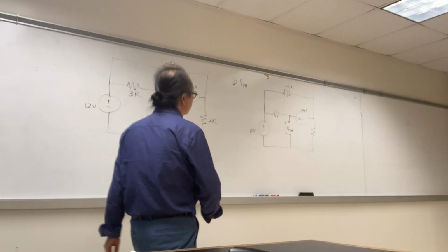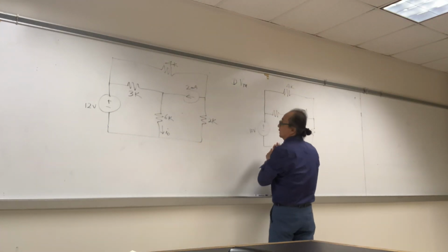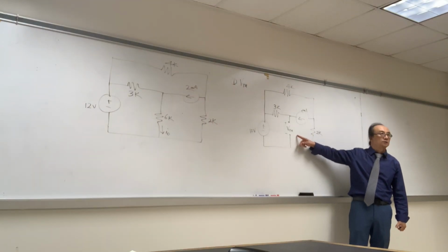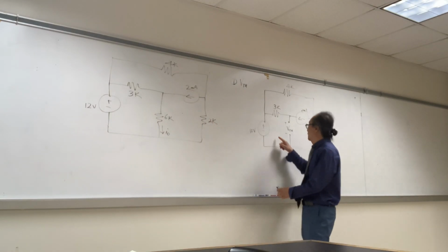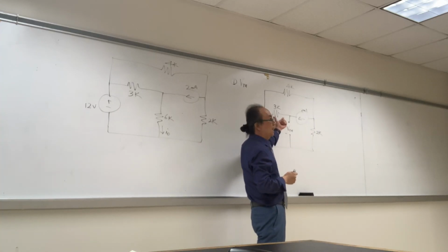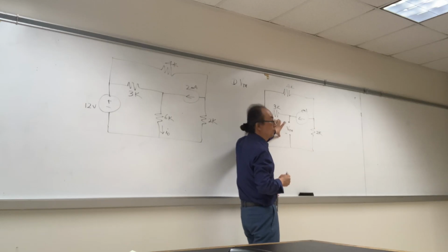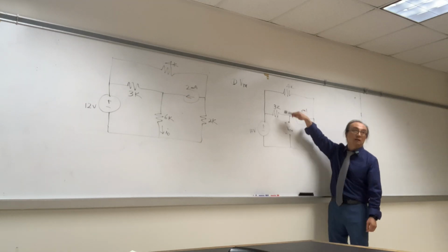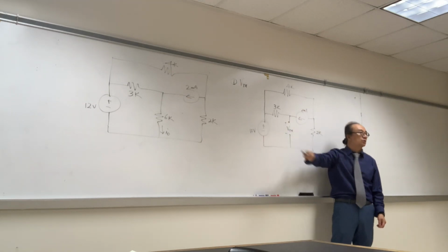Now, we need to just find the VTH in this circuit. How? Any suggestion? So in this circuit, find the VTH. We may want to do the KVL in here, right? We know the voltage, and if we can calculate the voltage across here, we should be able to find VTH. Current division? No. Current division, we can apply to one current source with two clearly parallel resistors. In here, no, because these two are not parallel, right? And also there is a voltage source, so no.